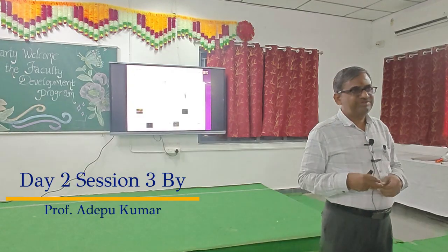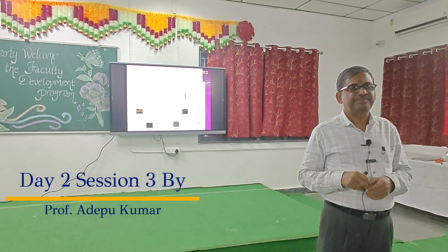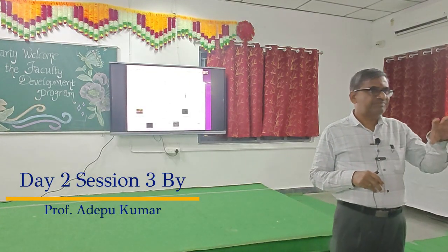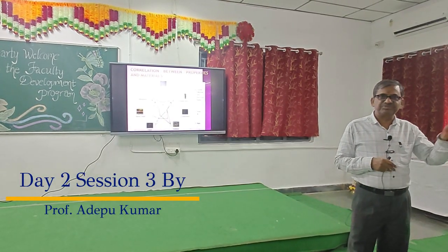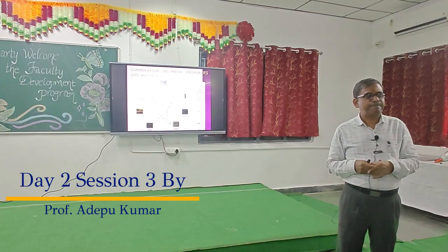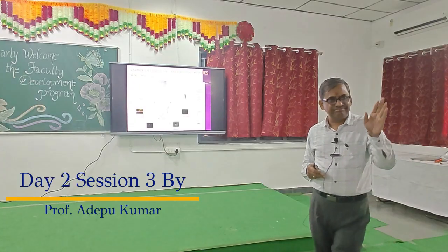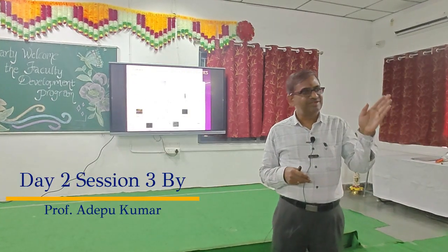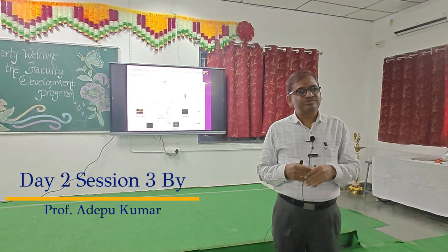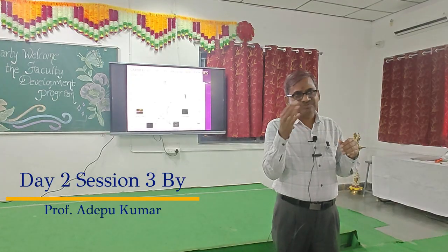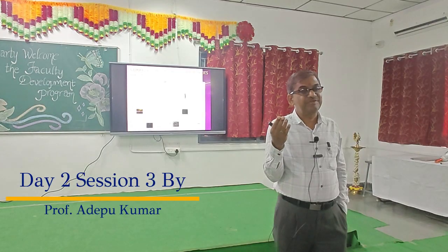Then you take the sample, then you can go for XRD, then you may get different phases. Then after identifying the phases, you can go to the literature for these phases. What are the properties of these phases? So Al2Cu is brittle, Al4Cu3 is a little more brittle, and Al2Cu3 is a little more brittle. So once you avoid the Al2Cu3 and Al4Cu3, I may get a solution.